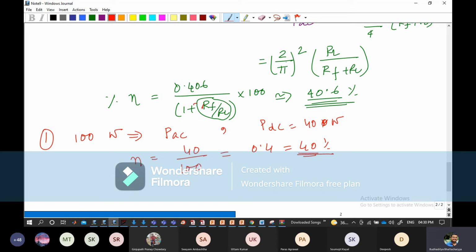So when we are considering the total efficiency or the power rectification efficiency, and if it is coming 40%, it means this is the 50 watt out of the 100 watt, which is due to the positive half cycle of the signal. Out of the 50 watt, 40% is getting converted. So if we consider the power efficiency, how much is it? This will be 40 by 50 multiplied by 100, which is around 80%. So if we consider the power efficiency, about 80%, the rectifier accepts only 50 watt and converts it to 40 watts of power. Clear?